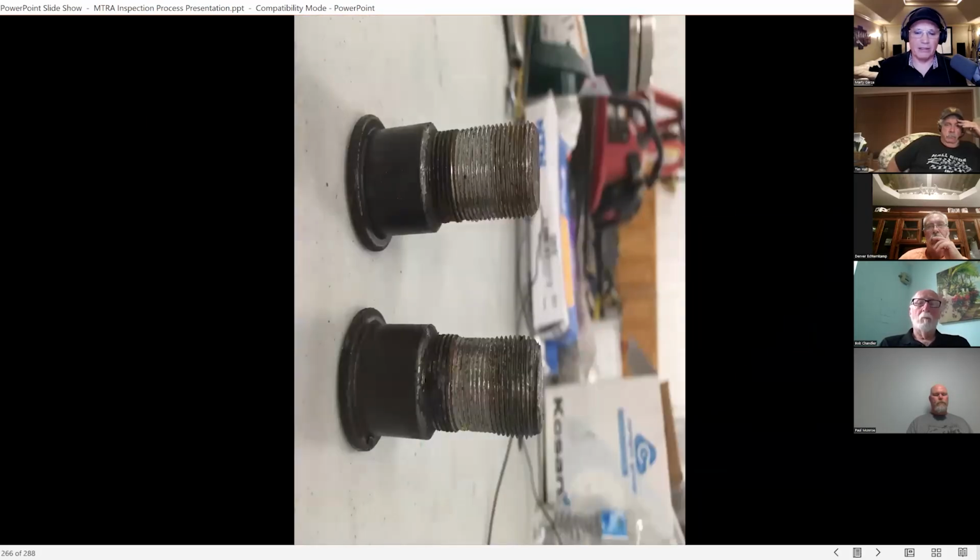Beyond that, the next one in that's kind of distorted is the wheel stud itself. From tiring up these trucks week after week, day after day, sometimes multiple times a week, crews that are in a hurry have a tendency of loosening all the lug nuts and just dropping the truck.